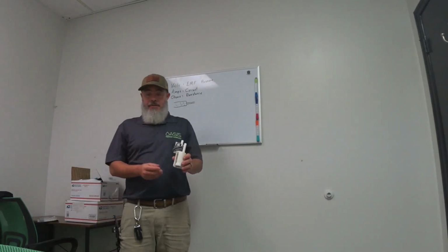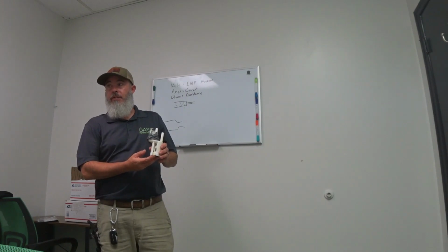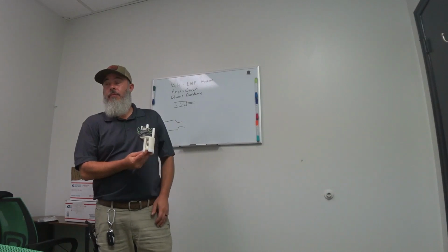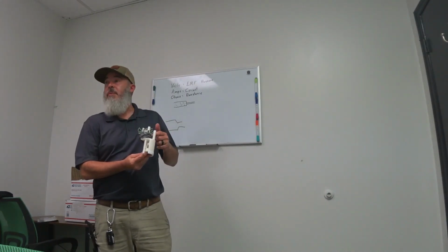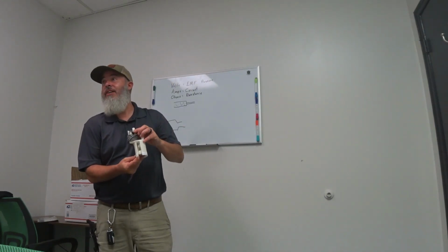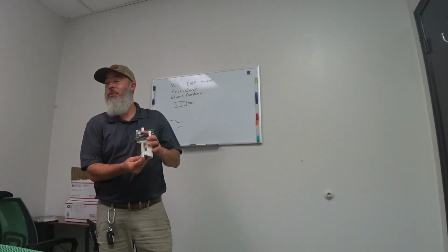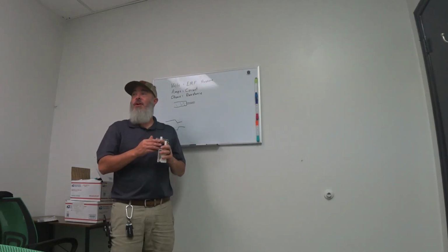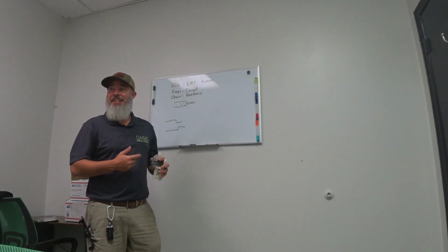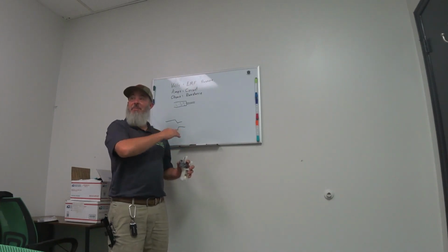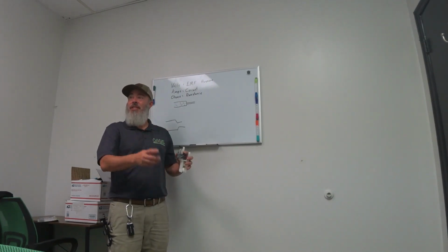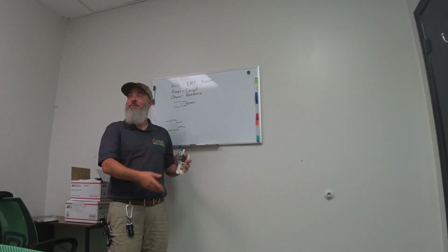And the opposite of that is that it goes into a fill cycle, right? So this is coming up as it's filling. It gets all the way to the top. And this is bad. This float came up here, but electrically, at the end right here, it's not sending the signal to the board. So it's going to continue to fill. It's never going to go off on a beep code because that can't damage the machine. It's got a standpipe in there, so it just overflows. It fills, it checks the float switch, fills, checks the float switch.